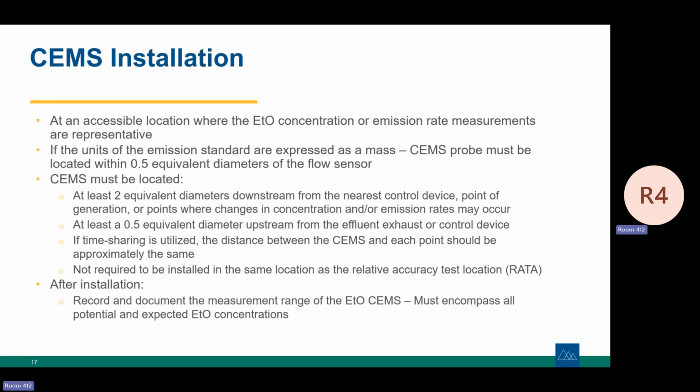Installation. This is language around making sure that you're putting your sample points in places that make sense. If you're sharing, it does allow for sharing sample points in an instrument. As long as you meet certain requirements, you can have multiple sample points in an instrument. Make sure they're approximately equidistant apart, and that you're looking at all possible concentrations in your process.